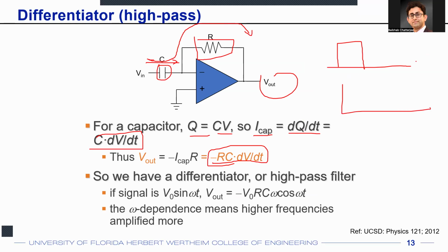So if this is time and this is amplitude, if you do an FFT of the square wave, and some of you who already know about Laplace transforms or have taken a signals and systems class know that for a square wave the FFT looks like this: you have amplitude on the y-axis, frequency on the x-axis, a fundamental at the frequency of the square wave, then 3 times the fundamental. So if this is f0, there would be a component at 3 times f0, at 5 times f0, 7 times f0, and so on.